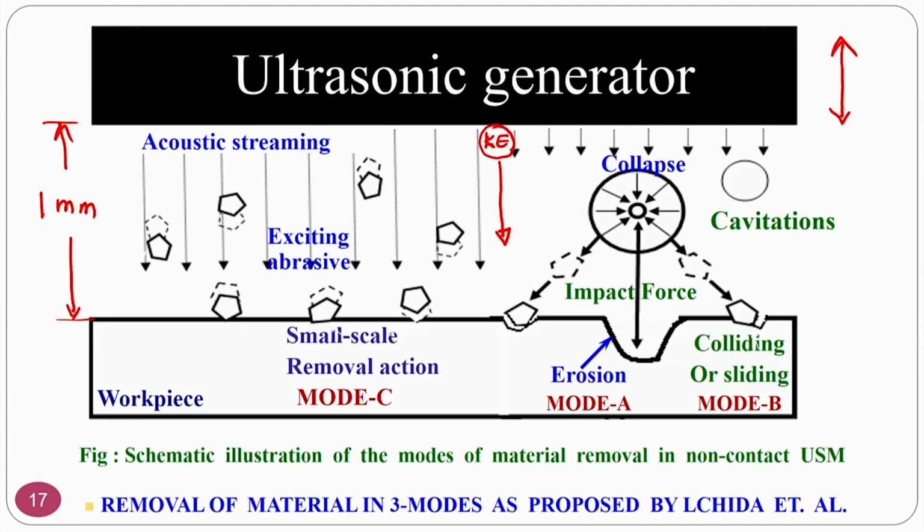If you see the acoustic streaming, normally the excited abrasive gains the kinetic energy when it is given to the abrasive particle here, and it excites, and it will come and hit the workpiece. So the material will be removed.